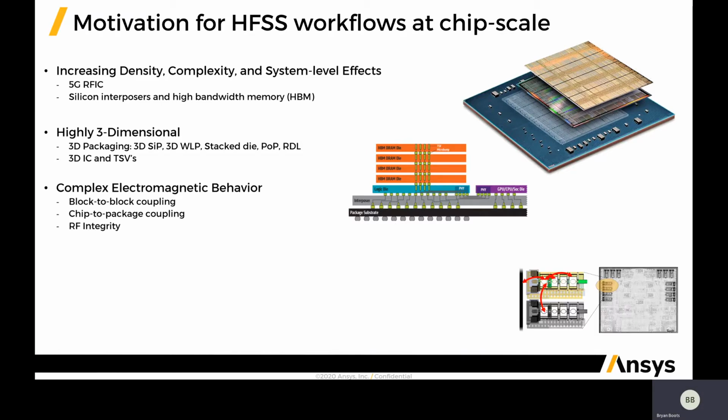And all of this combined is just creating a more complex electromagnetic environment where we need to better understand complex coupling mechanisms, be they block to block, chip to package, block to seal ring, and this emerging concept of RF integrity. So bringing a lot of what we've generally referred to as signal integrity workflows and concepts and pushing them onto the chip and better understanding these coupling mechanisms.